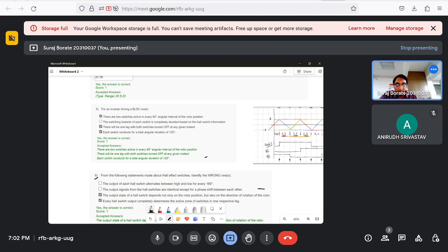Okay. Now we go here. So rotor of BLDC accepts DC input voltage. Wrong, right? It is because now we have magnets. We don't have the coil only. So there is no question of input voltage. Okay. Stator of BLDC motor houses a magnet. That is wrong. Okay. It is the rotor that houses the magnet and the stator has the coils. Okay. So it is ulta, the opposite. DC motor and BLDC motor is ulta.